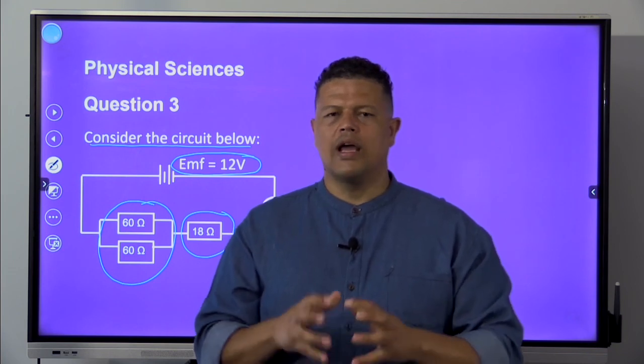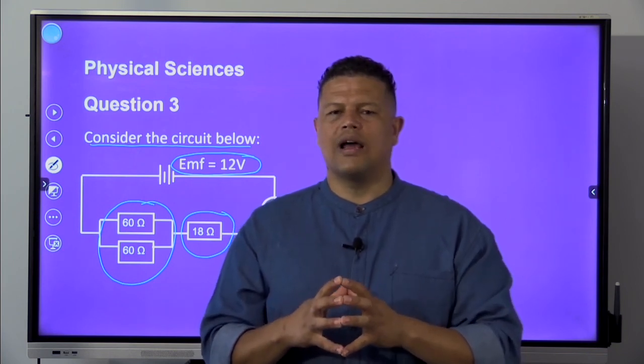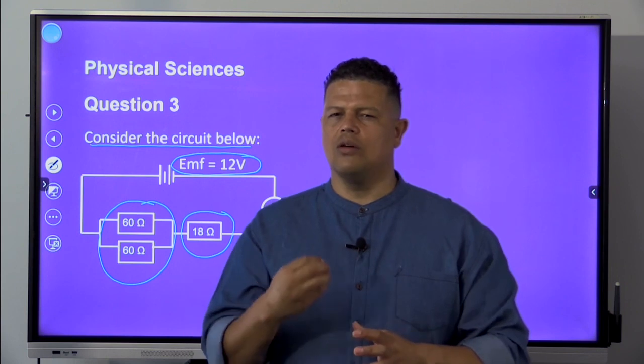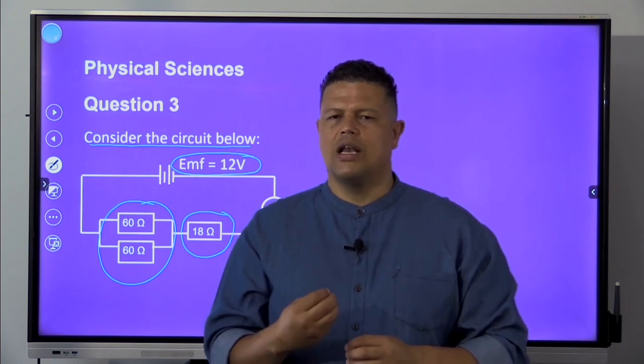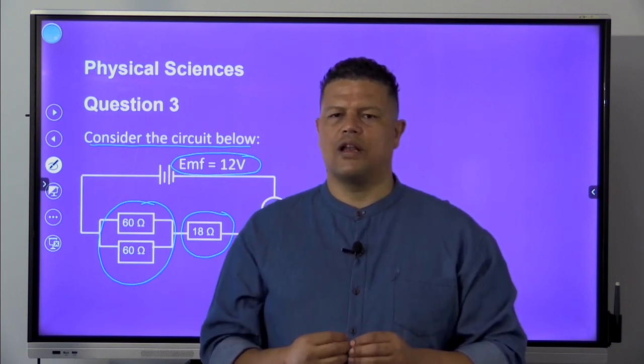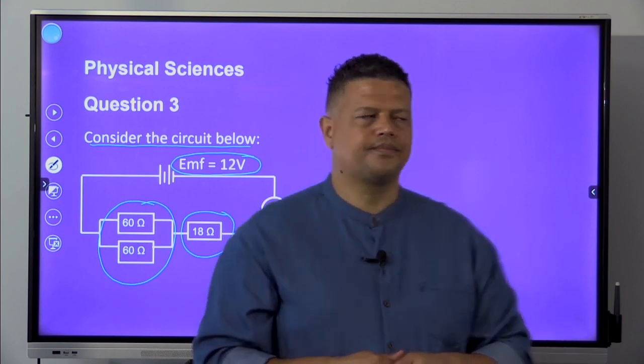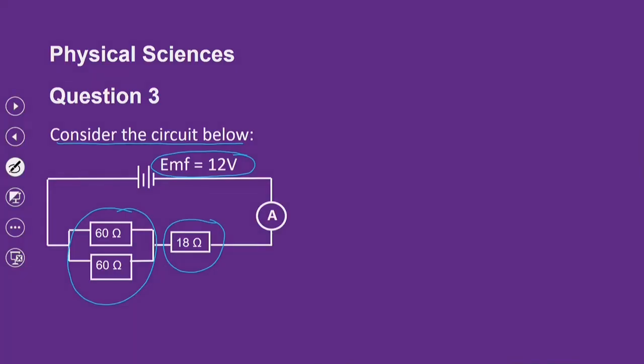Let's go and use what I've explained before. So without looking at what the questions are, let's see what we can calculate very quickly. Join me on the board. We can start off by looking at the equivalent resistance in parallel. It's only two resistors, so it will be 60 times 60 divided by 60 plus 60. And without a thought, that will be equal to 30 ohm.